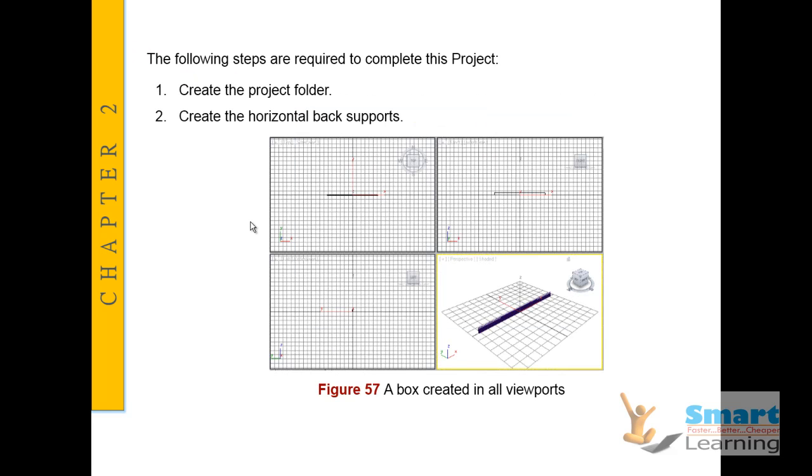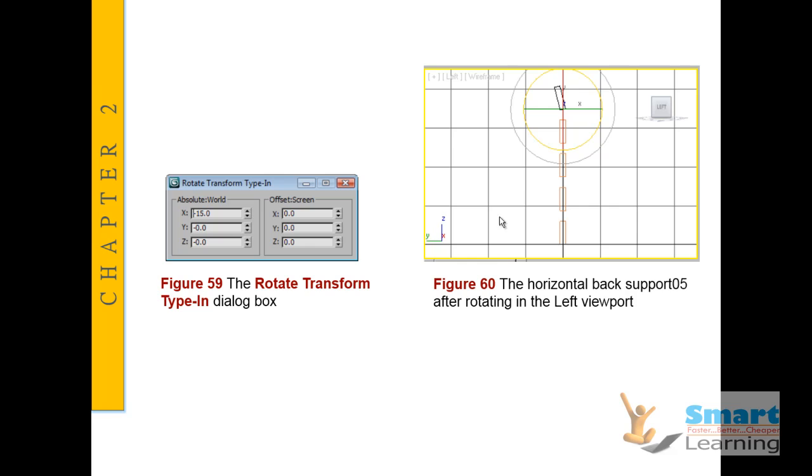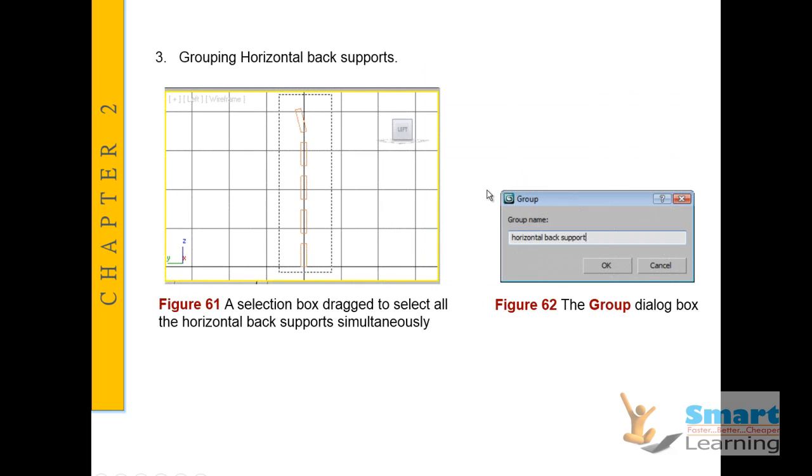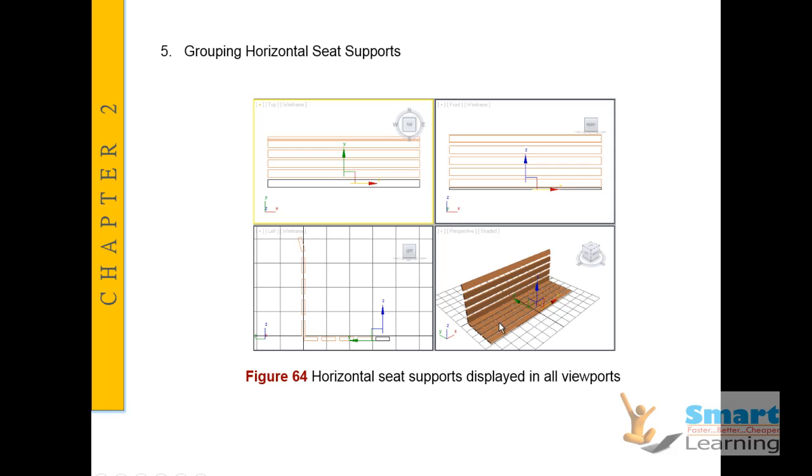So initially we will be creating the back supports, and we will be copying that to 5 different numbers, and after that we will be positioning the top one with a little bit rotation, and after that we will be copying this set to the horizontal location, so that this will be modeled properly, and like this your initial framework will be done. Let us start till this point.